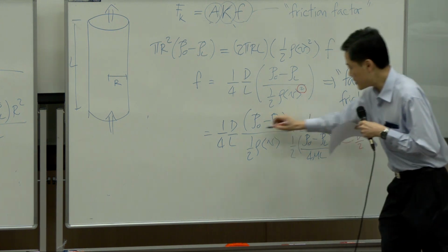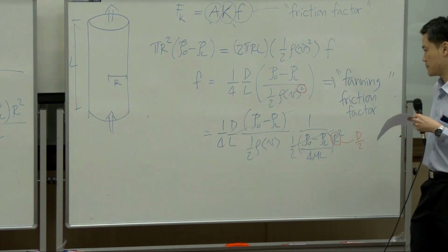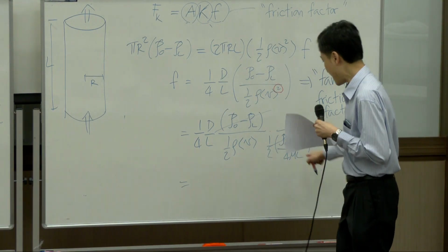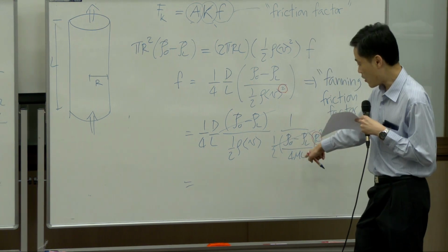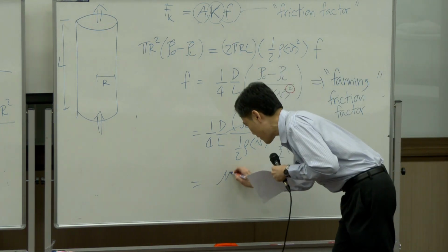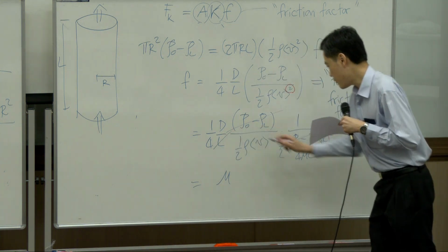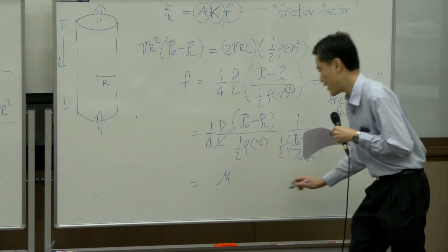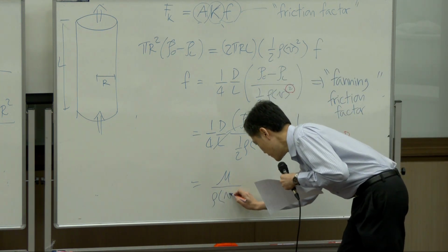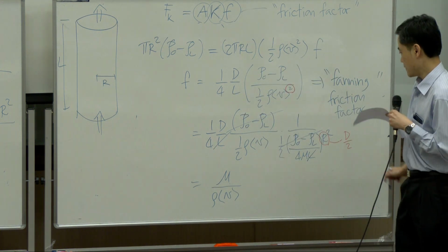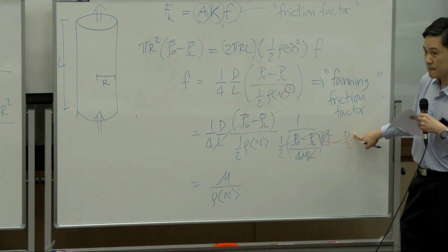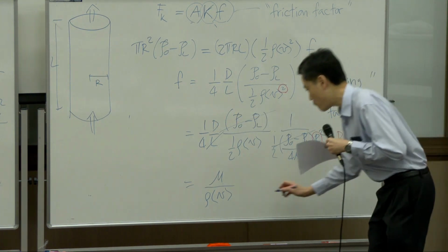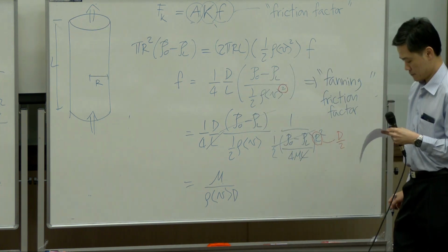And you see that this pressure difference would cancel out. Eventually, I have mu here as the denominator of the denominator, so it flips upward. You have mu up front. This L and L cancel out. Okay? I have rho V underneath here, so rho V. I have D here, 1 D. This is D squared, this is single D. Cancel out. You get 1 D left. All right?